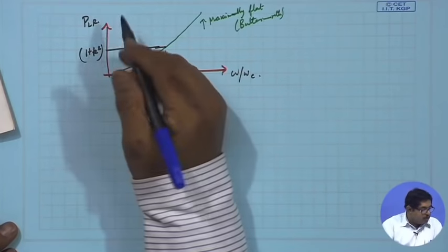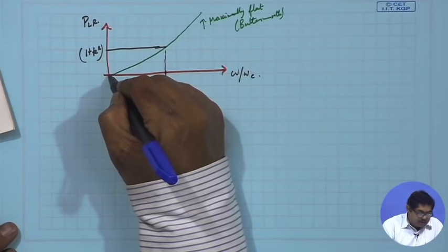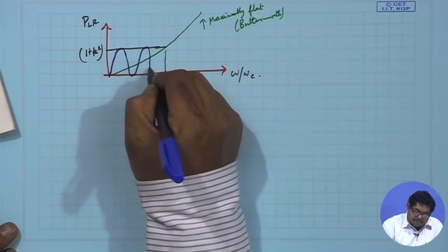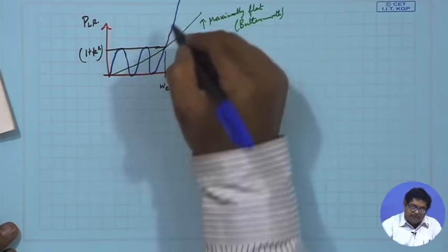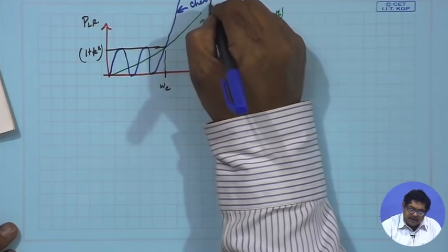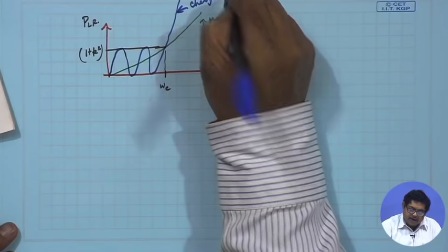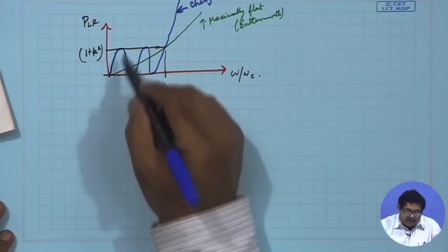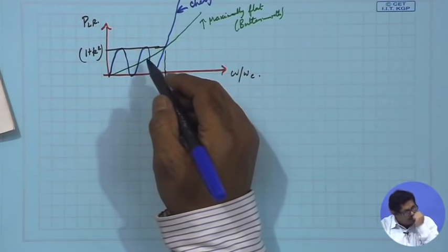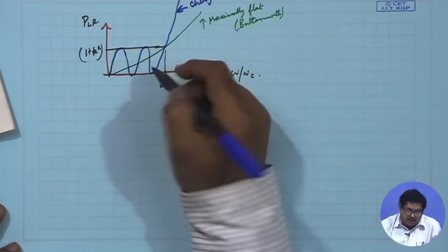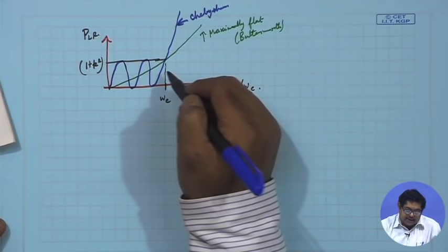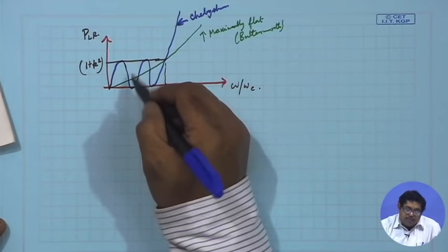Now, this is Chebyshev. Chebyshev has various forms depending on the order, but it ripples, whether there will be one ripple, one cycle or two cycles or three cycles, that depends on the order. But you see always they are confined between this and this. So, what is the advantage?